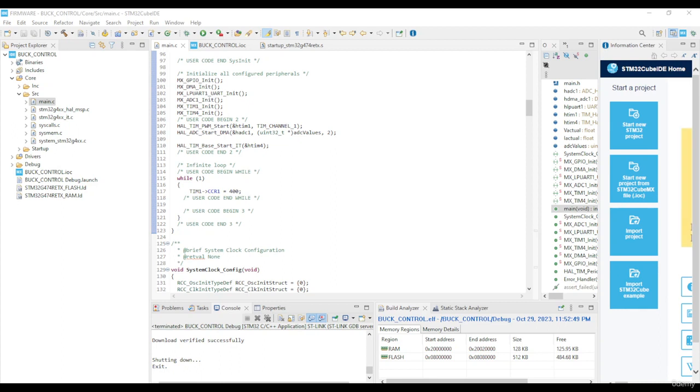In this case, we've confirmed the PWM is fine and can be changed, but the other two parts have not been confirmed, and that's essentially what will be demonstrated in this section. To run this, STM32CubeIDE actually has this great feature called live expressions in debug mode, but you actually have to set it up, which is as follows.